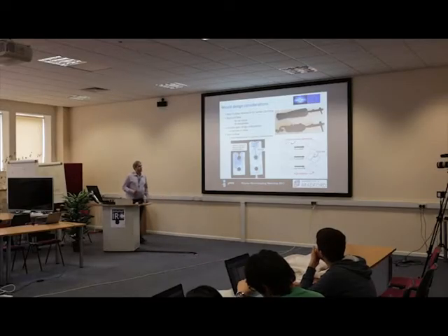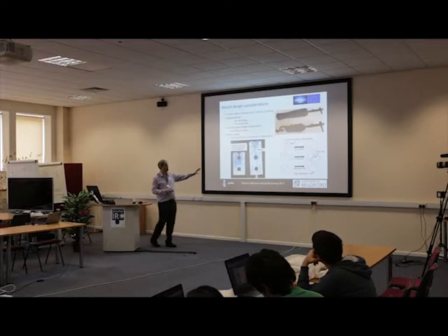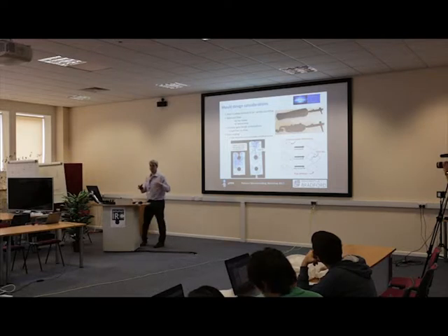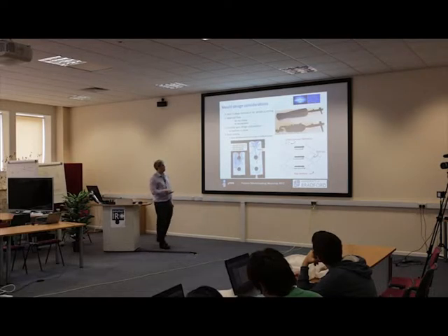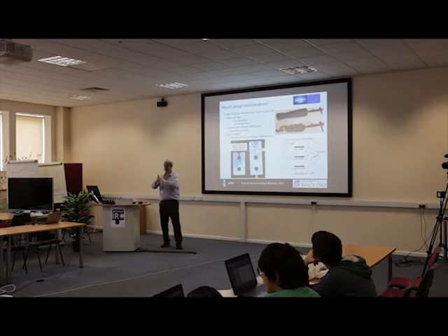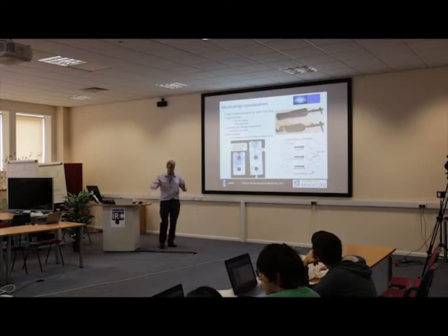So during that tool design process, we've designed the component at this stage to make sure it's suitable for the injection moulding process, but then we still have to think about things like where we inject the material from on that part design. Gate location can be quite challenging, because what we want to do is make sure we get a nice uniform pressure distribution throughout the part, but we want to avoid key problems like weld lines. Wherever we get two flow fronts coming together, the coldest part of the material coming into the cavity is actually at this flow front. So that cold material is not going to knit as well when it impinges on itself.